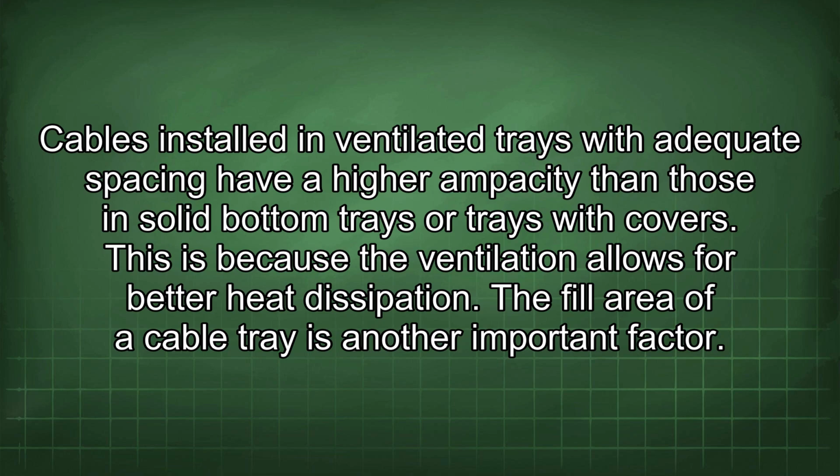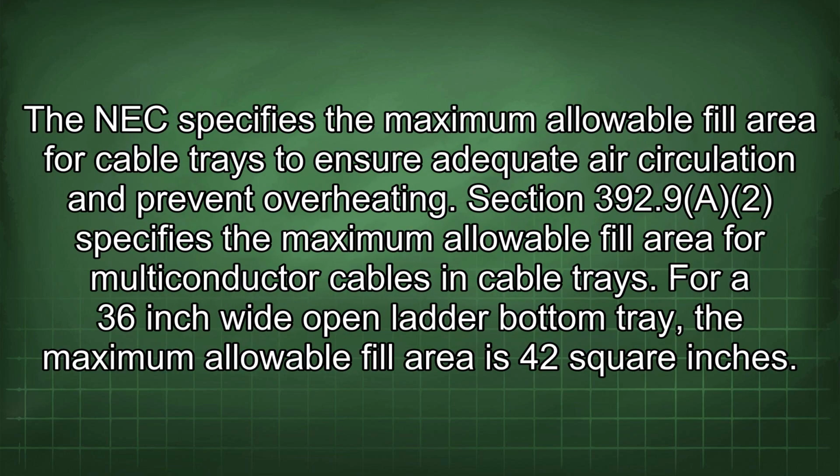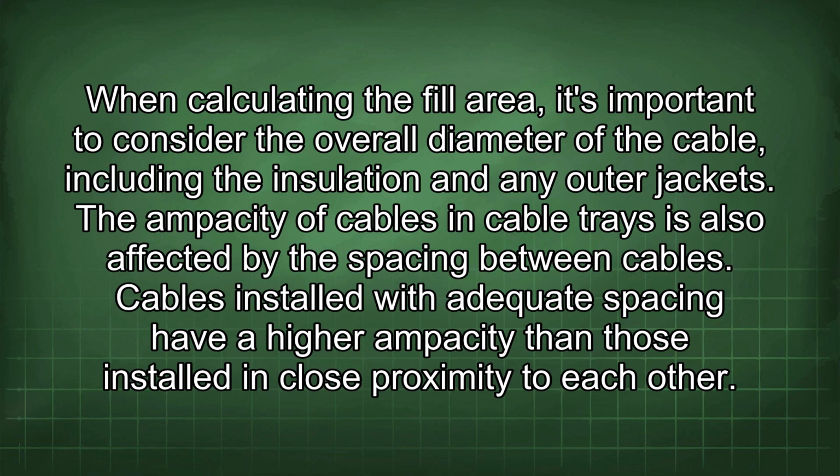The fill area of a cable tray is another important factor. The NEC specifies the maximum allowable fill area for cable trays to ensure adequate air circulation and prevent overheating. Section 392.9 specifies the maximum allowable fill area for multi-conductor cables in cable trays. For a 36-inch wide open ladder bottom tray, the maximum allowable fill area is 42 square inches. When calculating the fill area, it's important to consider the overall diameter of the cable, including the insulation and any